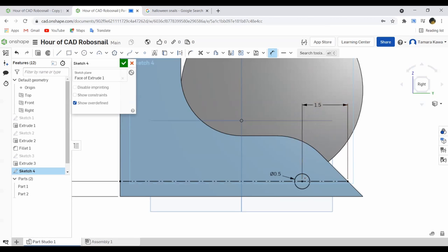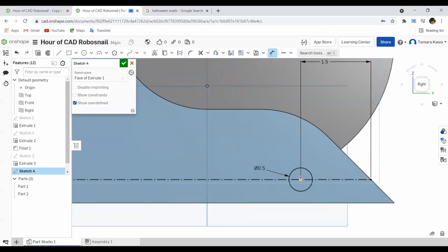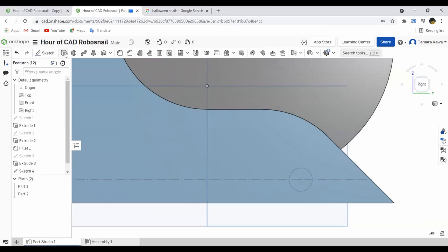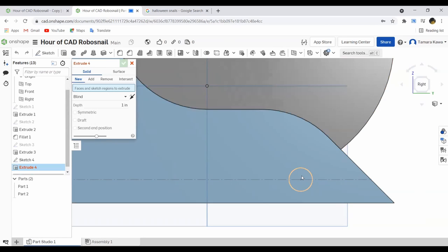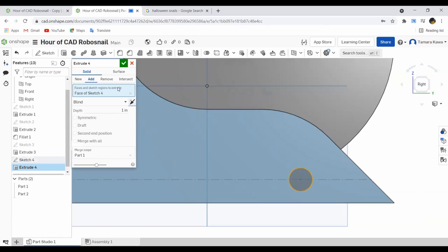Yeah, so again, for emphasis, point to point. Make sure you're going from the center. And again, your dimensions are going to be a bit different from mine if it makes more sense that way. So if you're not following the dimensions exactly, that's okay. What matters to me is that you're learning how to do this. So with that, it's time to cut out some holes for our axles. So we're going to click on that check mark and we're going to go back to that extrude tool that we love. And we're going to click on this hole and we're going to say remove.